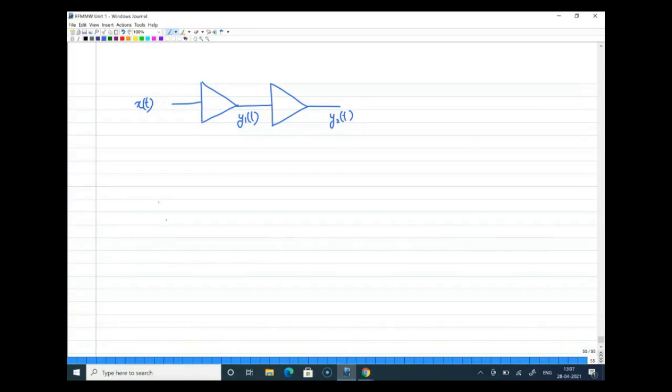The rest of the things remain the same, whatever we have taken before. This is a nonlinear system, and this is also a nonlinear system. Alpha 1 and all those things remain the same. Now we'll quickly look at the products. Look at the frequency components here. At the input you have omega 1 and omega 2, the input frequency components having amplitude A. For the first term, all the coefficients will be written with alpha, and for the second term, all the coefficients will be written with beta.